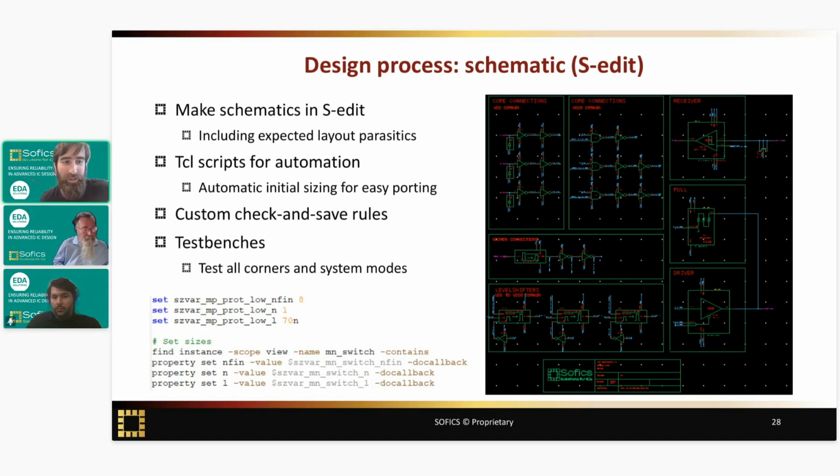Yes, absolutely. Regarding tool usage, on the technology installation side it is very similar. Metal coloring is one example that needs to be installed correctly, but once it is installed, it runs very fluently. But layout complexity really jumps a lot from CMOS to FinFET and from FinFET to gate-all-around. The best indicator for this, for me, would be the size of the design rule manual, which grows 10 to 20 times easily. A 1,000-page document plus isn't very uncommon.